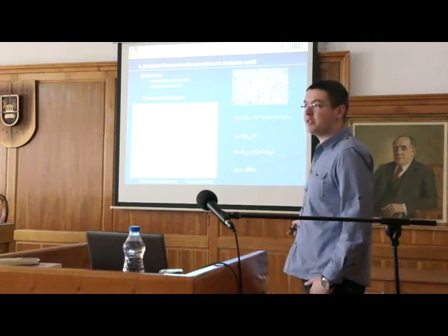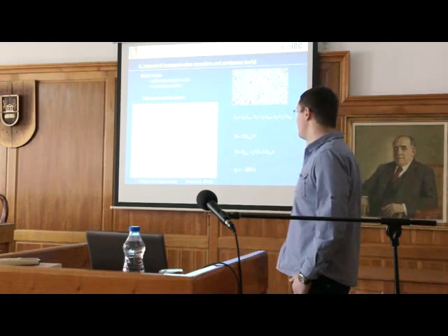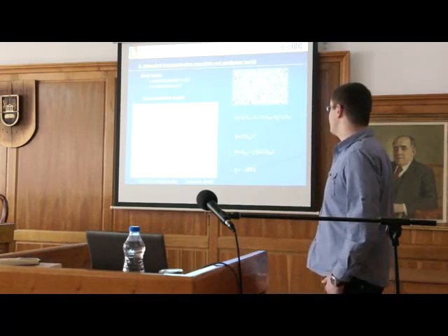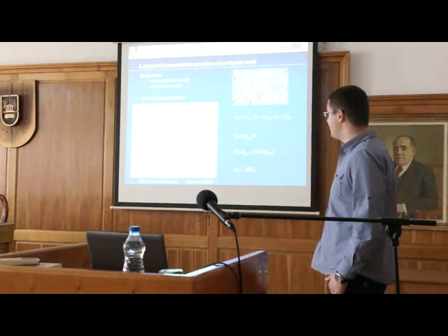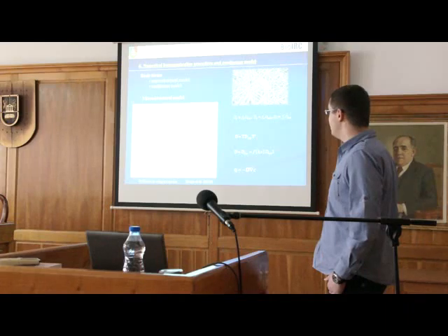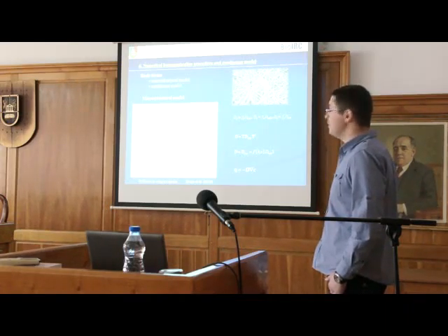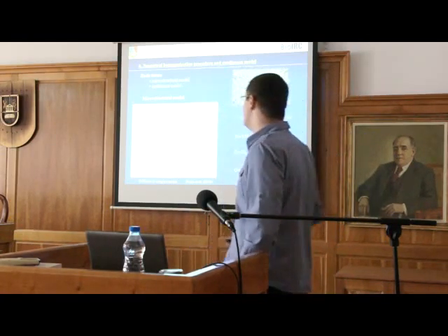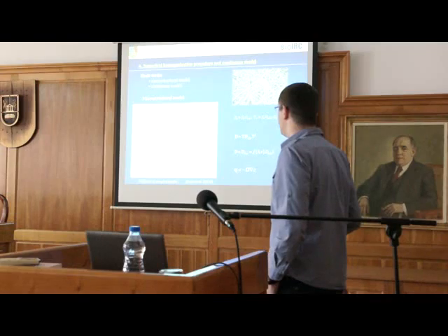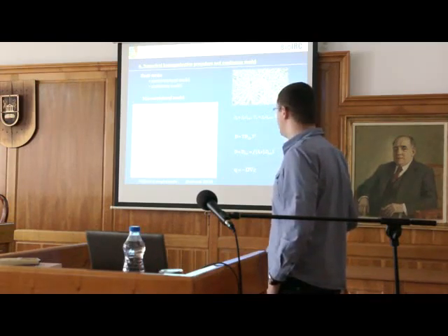We have real fibers inside this reference volume, and for example, for some point A in this reference volume, we find the closest fiber, and we find the distance from that closest fiber, and using the scaling functions from the previous slide, we can calculate the diffusion coefficient for that point.